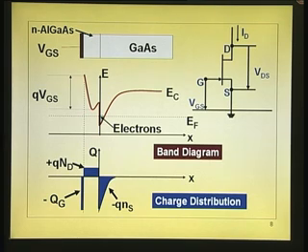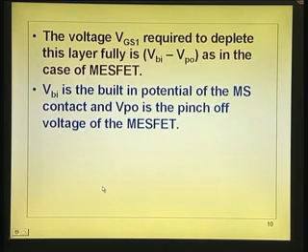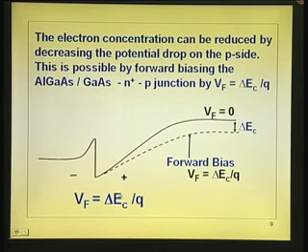Now, you can see that the charge here can reduce by applying more negative voltage here. This is a situation where the entire thing is just depleted. You increase the voltage by an amount equal to minus delta Q by C, the charge will go down to minimum. That is the off voltage. So, this is what we have done here. We apply a forward voltage across that layer to bring the charge to 0.